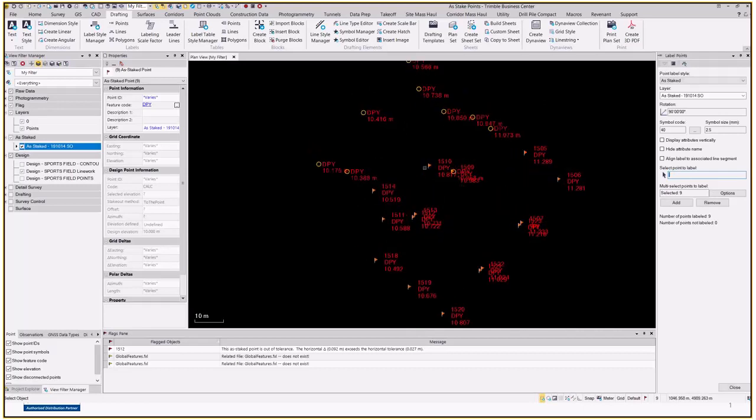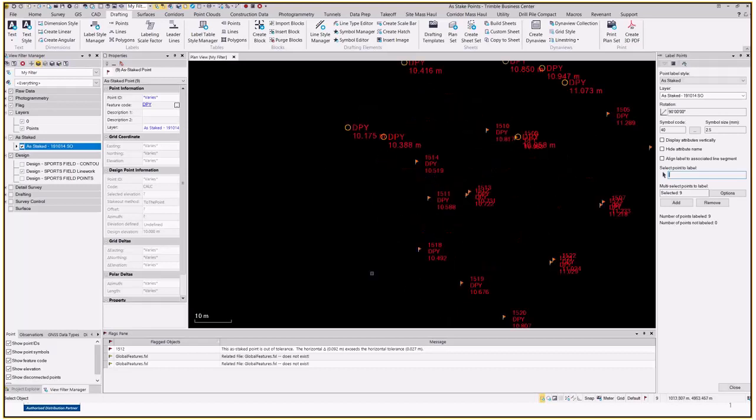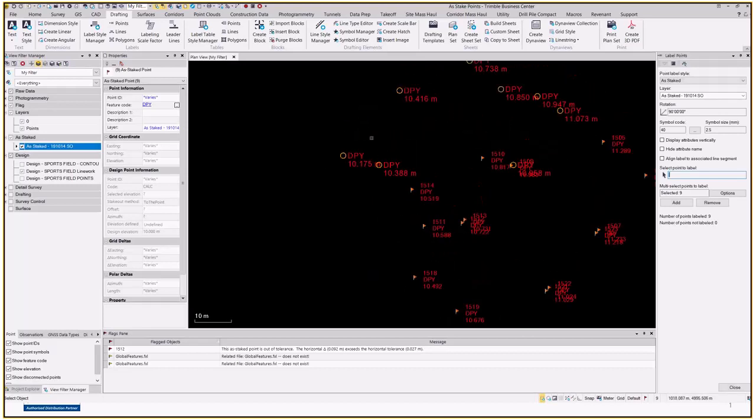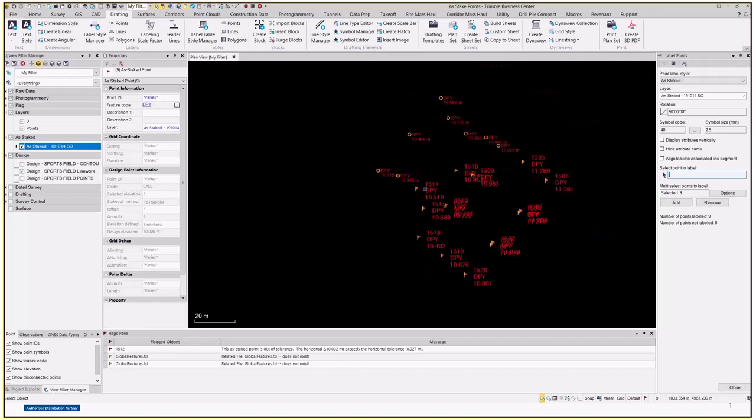At the moment, I've got this text style set up so that the text will be set to 2.5 millimeters on the plan sheet. So this text will vary depending upon the scale preset in my project settings. I think at the moment it's set to about 600, and I'll go back through in a minute and change that down, once I've looked at what scale I probably will get my plan sheet at.